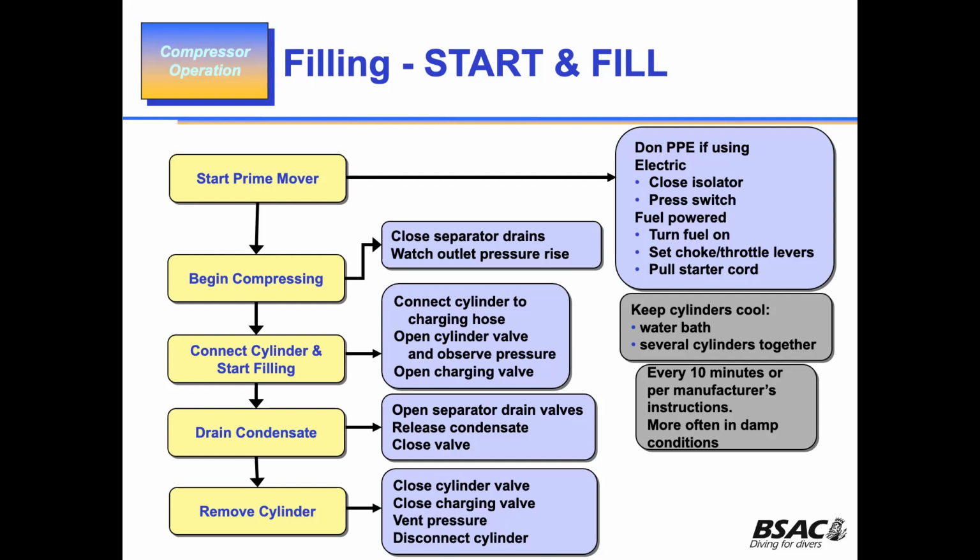Close the cylinder valve, close the charging valve, vent pressure, disconnect the cylinder. And again, you'll see how they work. It doesn't take long for people of your ilk to pick up filling cylinders on a compressor, right? You're all clever enough to do it. If an idiot like me can do it, you can do it.